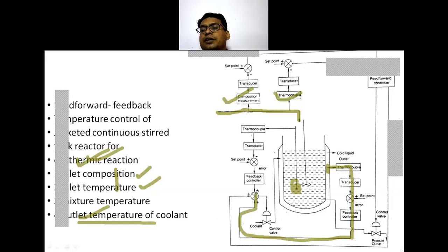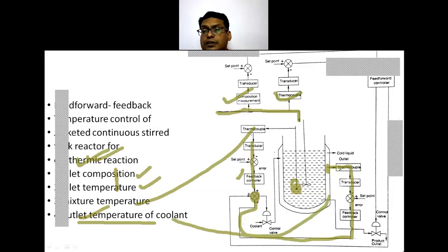So this comparator becomes more and more important, where the two feedbacks are provided. One is from the temperature measurement, the mixture temperature. Then the outlet temperature of the coolant. So two have been added, and there is also a third thing coming into this comparator, and this is from the feed forward controller.